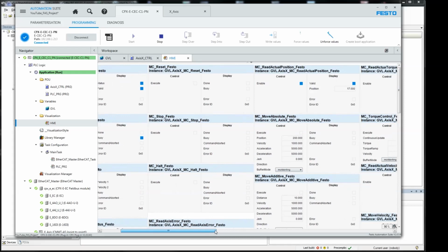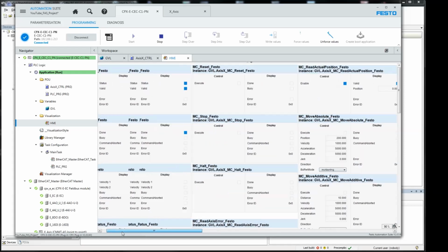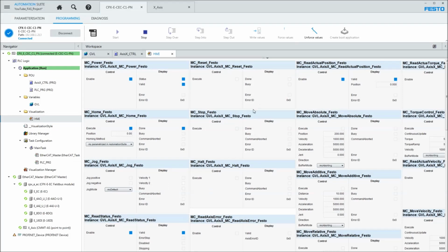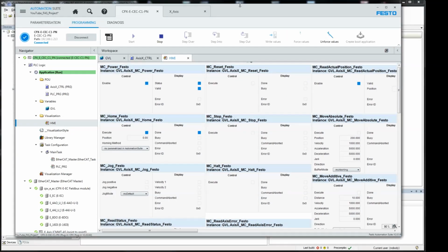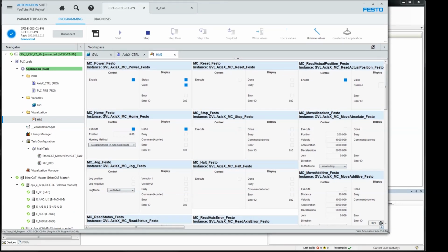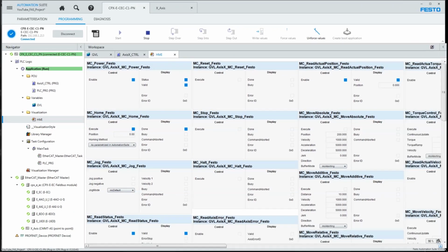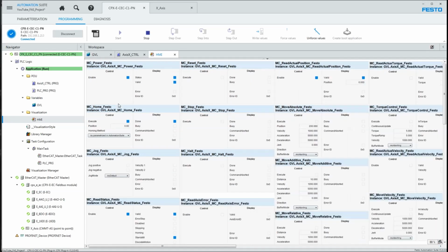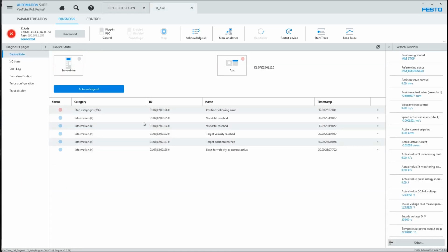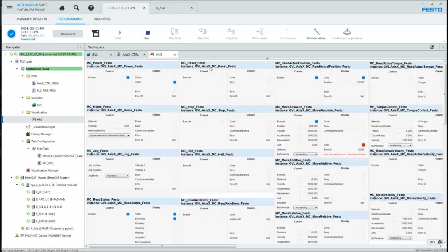You can zoom in a little bit. There's a 0 here. Maximize this here a little bit. Zoom out a little bit. Hopefully you guys can still see this in the YouTube video. But basically, let's say I've got a parameter here. I want to move execute, so I turn the home off. Execute this move, and it just moved. Of course, I got a general axis error here because I made it move 100 miles an hour, and I got a following error here, and that's to prove a point.